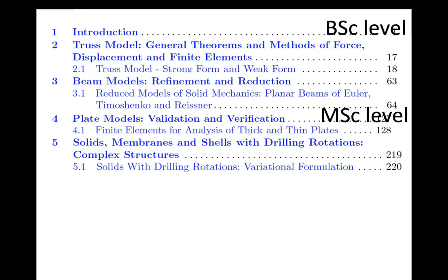Then you move on to the master's level. For example, we studied the plate model, and one topic that I haven't discussed here is very nicely representative for plate models. These are topics which are certainly core knowledge of using finite element models. That's called validation and verification. So what is validation? What is verification? Validation is the fact that you have chosen the right model. With respect to your goal, what you want to represent, you want to find a sufficiently refined model with all the set of equations needed to get meaningful results.